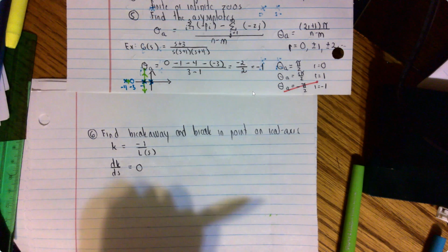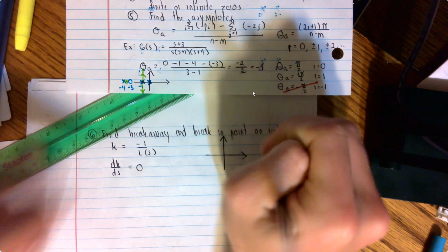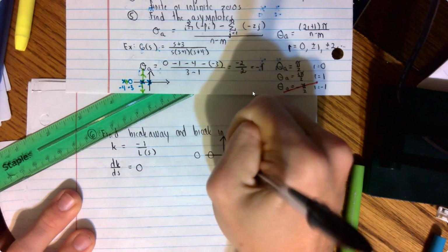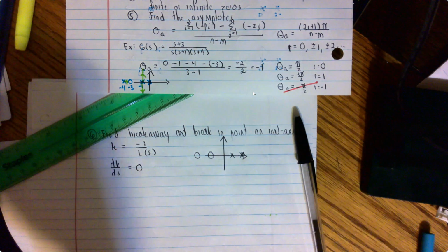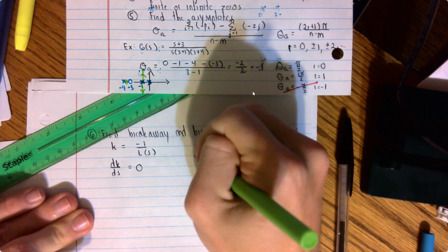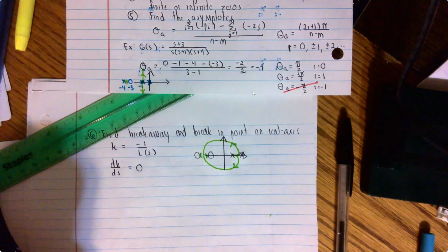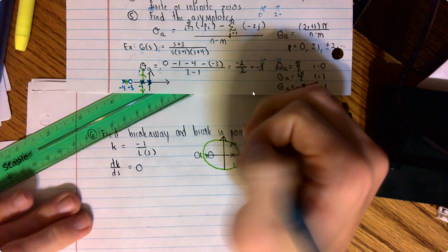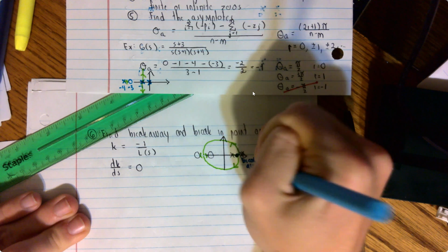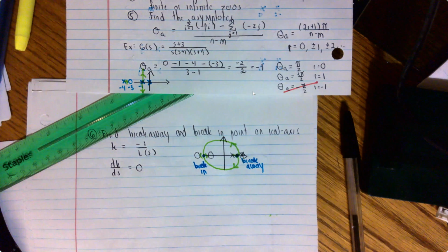And so notice that your break-in and breakaway, when I mentioned those, what those are is literally if you have 2 zeros over here and say you have 2 poles over here. And so this would be the direction basically that you have. So this would be a breakaway point right there, because you're breaking out of the x-axis and you're re-entering it at this point. So this is called a break-in point. So that's a break-in versus breakaway point.